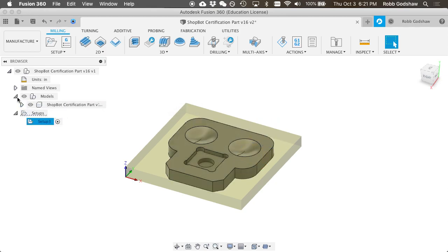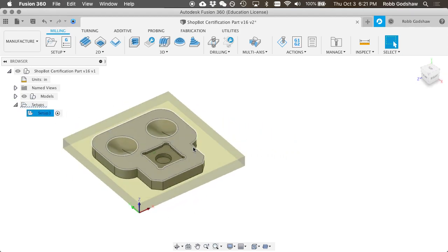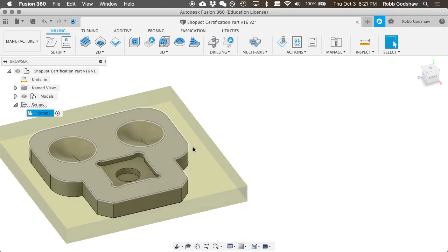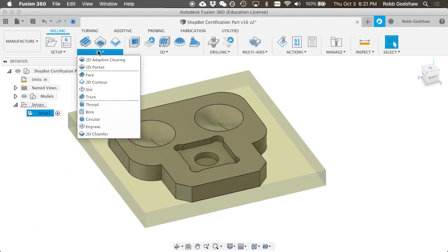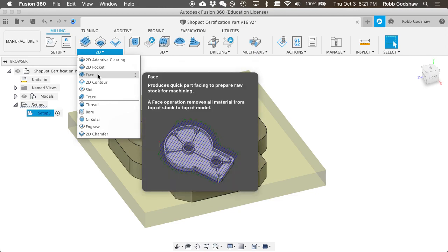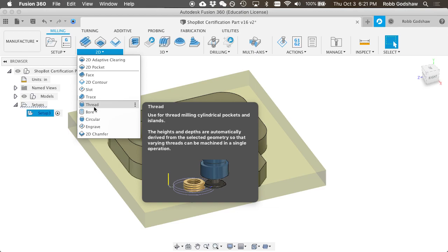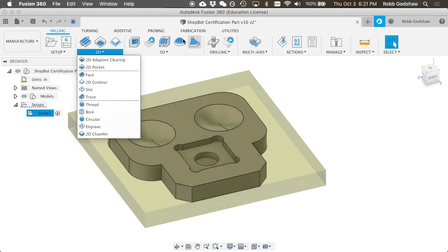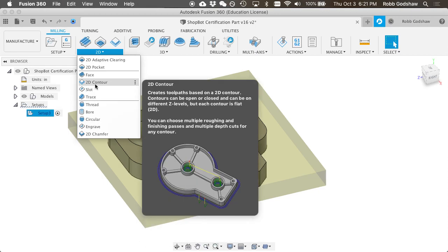Now that we have a setup that we like, we can begin our tool pathing operations. And just to give a quick summary, our goal here is in the 2-dimensional, or really the 2.5-dimensional plane, because these things are capable of doing depth. They just don't move in the 3rd dimension while they're machining, typically. I'll start easy. I'm going to do a contour on the outside.